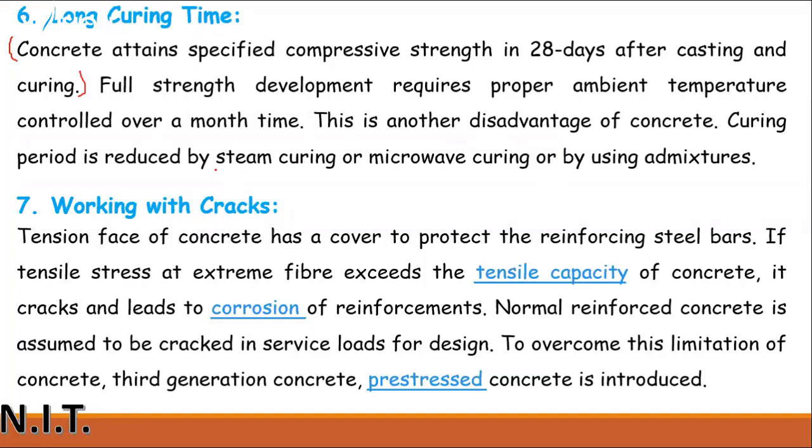Curing period is reduced by steam curing or microwave curing. If you provide steam curing or microwave curing or use admixtures, then you can overcome this time period. The same specified compressive strength can be attained within 2 days, 3 days, 5 days. You don't need to wait for 28 days.